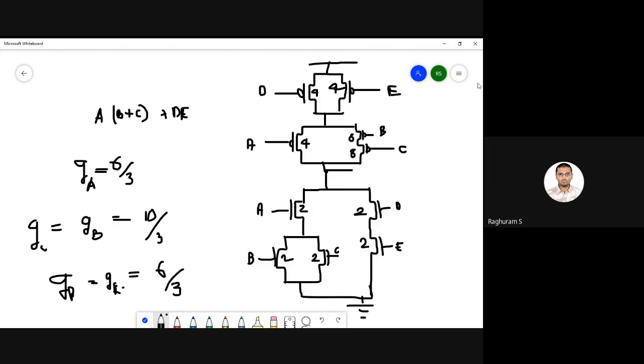Okay, so this is about compound gates. The whole idea is this whole function, right? We implemented F equal to this. We don't have to implement this as a separate AND gate or OR gate and one more OR gate. We can implement all this in one single stage of logic. So that is the idea behind compound gates. How do we make it faster? We make it faster by implementing all of them as one single stage. Even though the stage might be quite complicated, it might be cheaper than an ordinary function. So that is about compound gates.